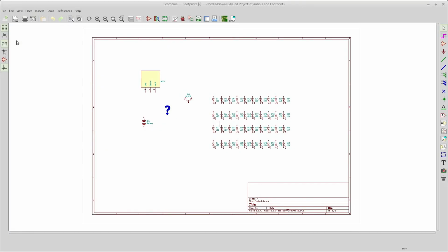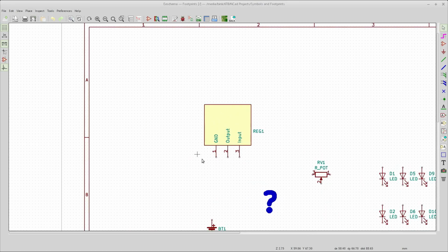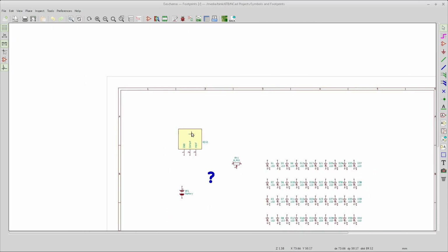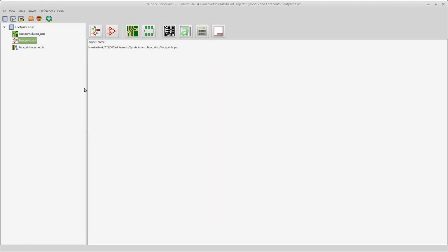And, well, to show you this, for right now, this is kind of the rough idea that we had from the previous video of maybe a circuit you might make, and you would wire it all together. This thing right here is the logical symbol of the thing that we just designed the physical component for in Fusion. Now this right here can open up what they call a footprint, which I'll show you. There's nothing there, but I'll show you.